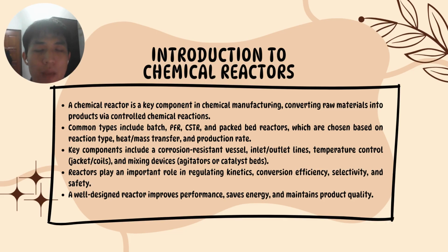So there are several common types of reactors, including batch reactors, plug flow reactors, continuous stirred tank reactors, and packed bed reactors. The choice depends on factors like reaction types, heat and mass transfer needs, and desired production rates. Each reactor system includes key components such as a corrosion-resistant vessel, inlet and outlet lines for reactants and products, temperature control systems like jackets or internal coils, and mixing devices such as agitators or catalyst beds depending on